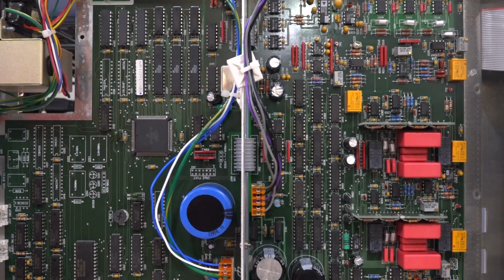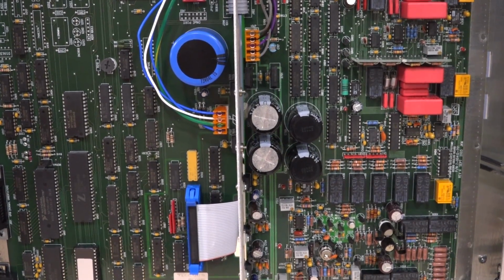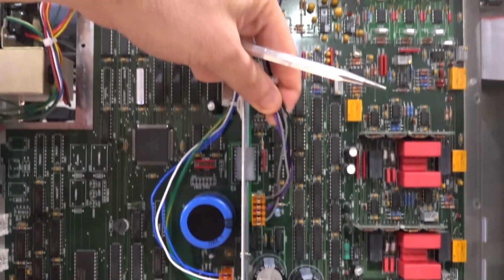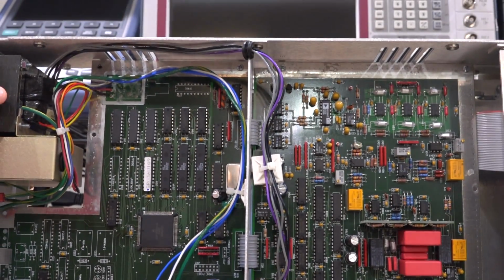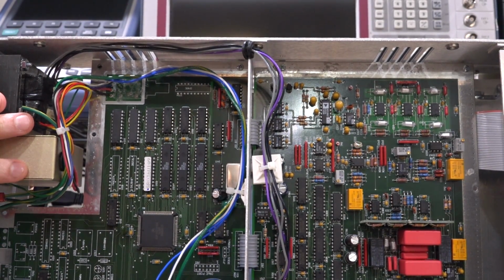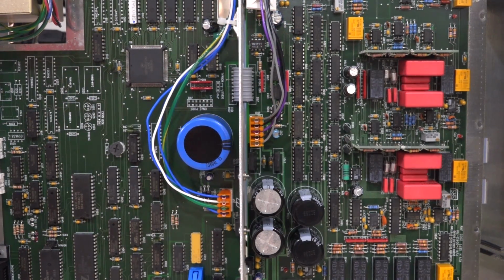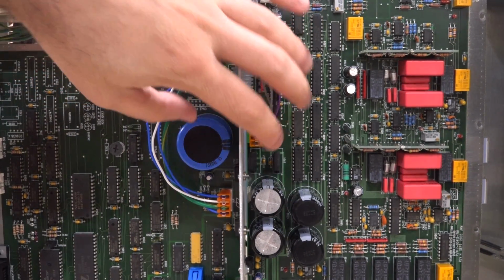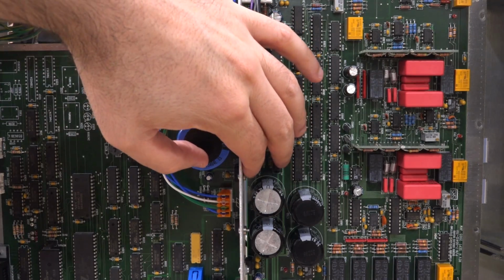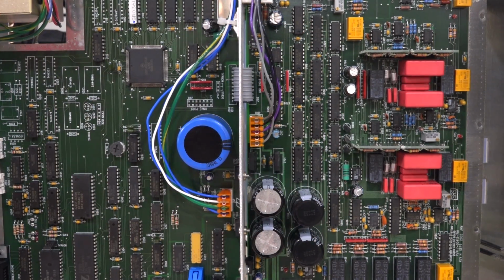So this entire board is powered, otherwise we wouldn't get any voltages coming out. And this is where the power comes from, right over here, and it's coming directly from the transformer. So if the transformer is working and is feeding this side, it must be feeding that side. We can check that to make sure it is working, but I'm fairly reasonably sure that it is. We have two full bridge rectifiers over here and the capacitors for that power supply. We can certainly check that to make sure those are okay.